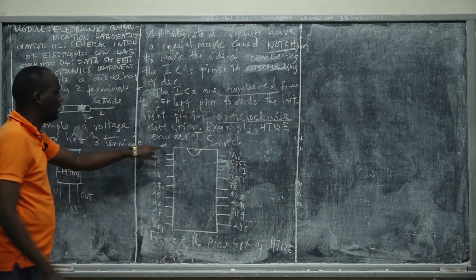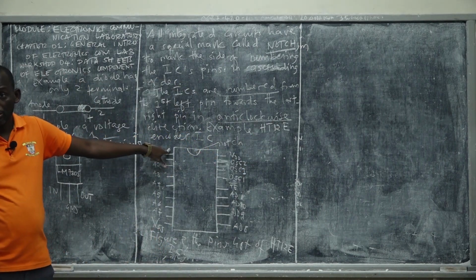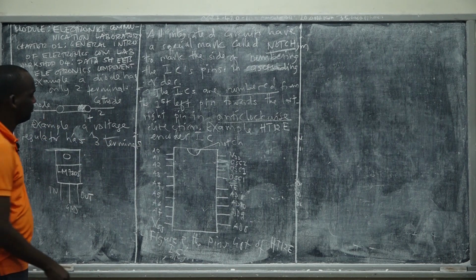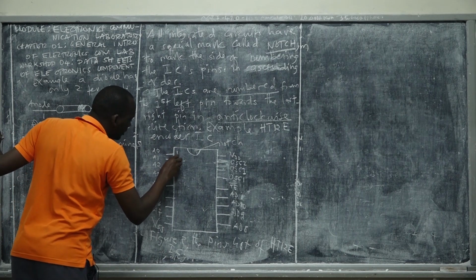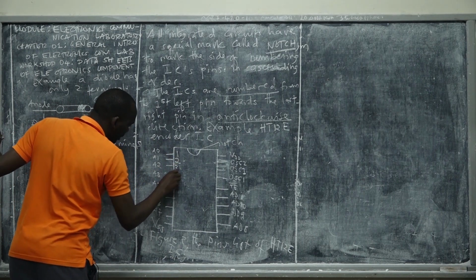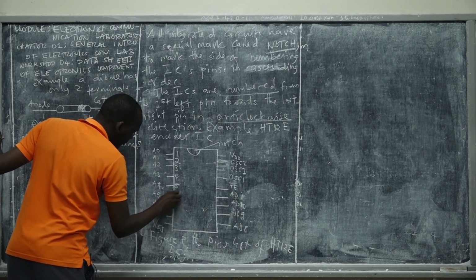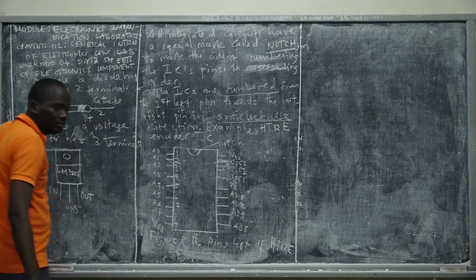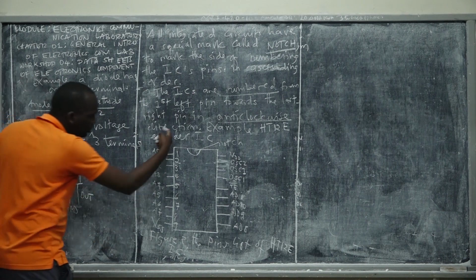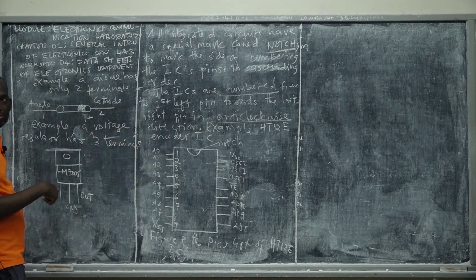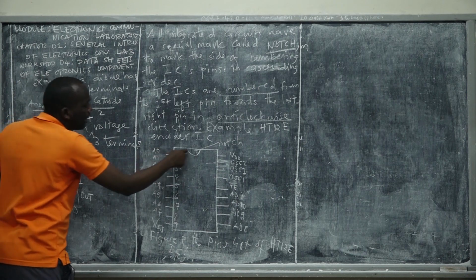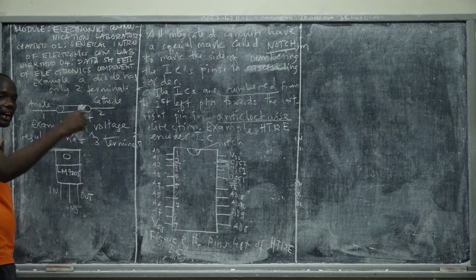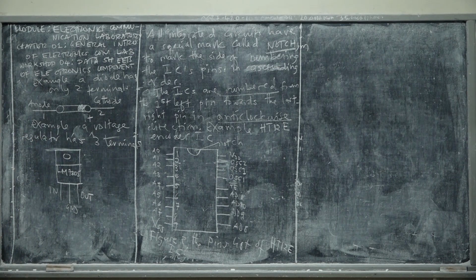So this is the first left pin, right? Okay, I said stop drawing. This is pin number 1, pin number 2, pin number 3, pin number 4, pin number 5, pin number 6, pin number 7, pin number 8, pin number 9. Then we continue anti-clockwise, right? We don't count 1, 2, 3 again. No. We just go anti-clockwise around the integrated circuit.